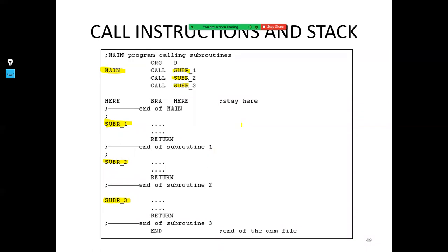If you have a program that is calling, for example, subroutine 1 10 times, we have to write subroutine 1 just 1 time. So the size of the code will be reduced, which means we are reducing the ROM memory needed to store this code.